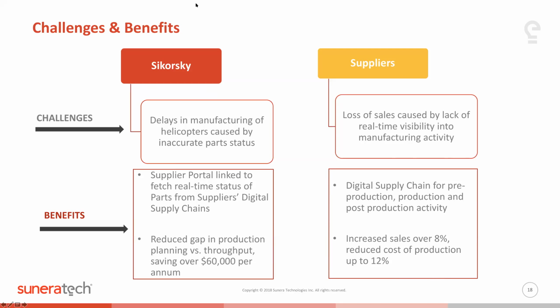But by attaching a 2D barcode to all of the part numbers as they go out into the shop and as they're capturing data, I now know where everything is currently. It's live data. It's constantly being updated. So I know where parts are, how long they've sat at each process, how many different jobs are out there for the same part number.